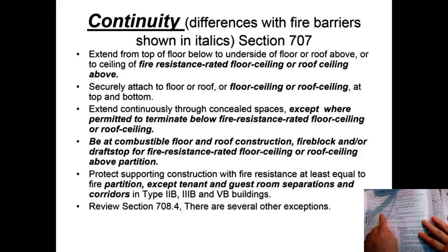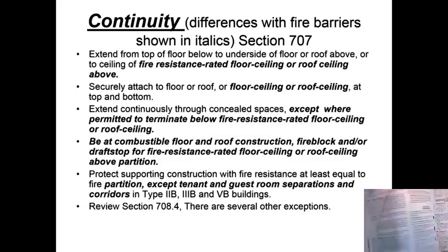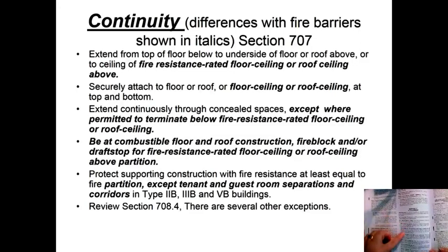Waste and linen collection rooms. It tells you here 1 hour, and it doesn't have an or sprinkler system option. It's saying you have to have this separation here. So that's something that you need to go back and look at. Make sure that you look at all of these areas that you see in here for fire barriers.